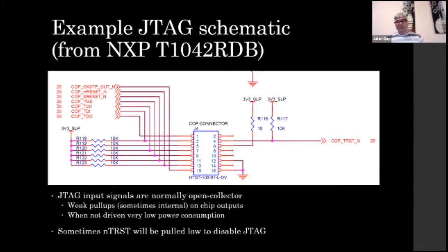So if you're trying to retrofit JTAG onto a board which doesn't have it, you may find that you need to add some pull-up resistors and such things.